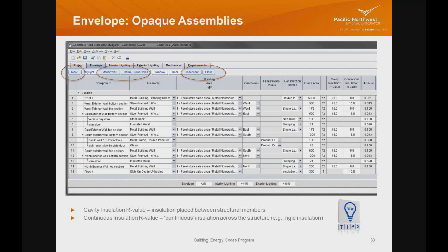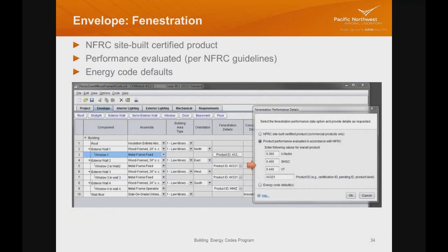Even though that might look like a blanket spanning over that structural member, if it's compressed such that there's thermal bridging going on, that is not considered continuous insulation, it's considered cavity insulation. Continuous insulation is truly unbroken insulation across the whole plane of the assembly. So try to be thoughtful on the values you're entering in those two cells with respect to thermal bridging going on.